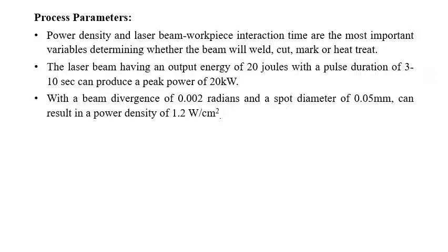As I told in the first point, these variables, power density and laser beam workpiece interaction time, are important in determining whether the beam will weld, cut, mark or heat treat. For a rapid heating of a surface without melting, a highly focused beam producing power densities of only 1.5 x 10^2 to 1.5 x 10^4 watt per centimeter square is used.